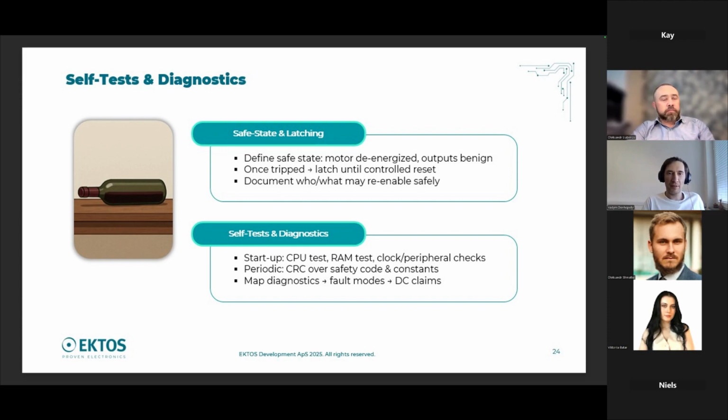Yeah, thank you, Alexander. And also, if you look at non-safety-capable MCUs, diagnostics will take quite a lot of resources. Even if you use a library from the manufacturer, it takes a lot of computation time or MCU time, and it also requires flash memory to hold these libraries, and it could be quite heavy for implementation.